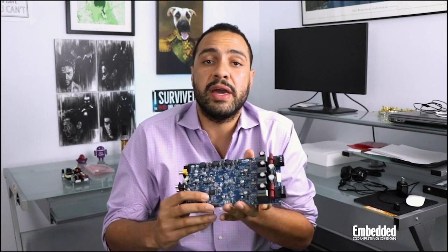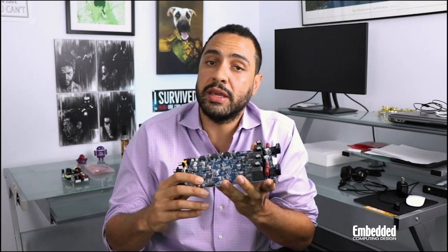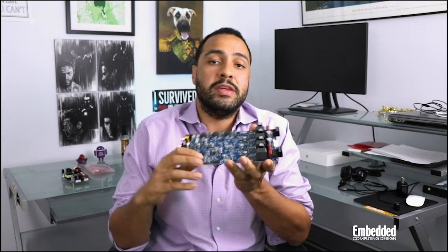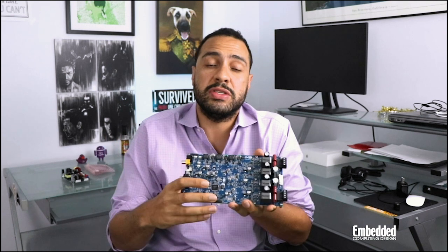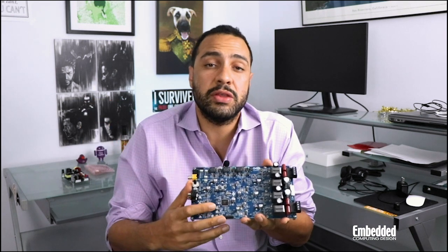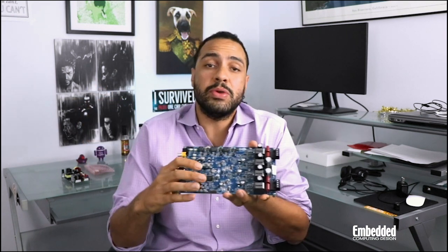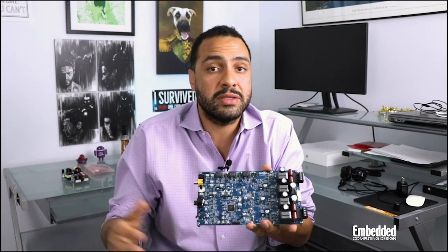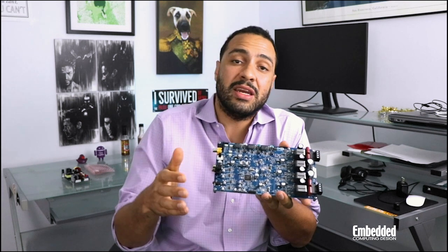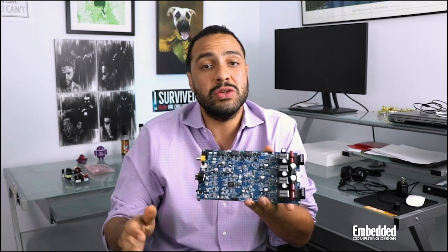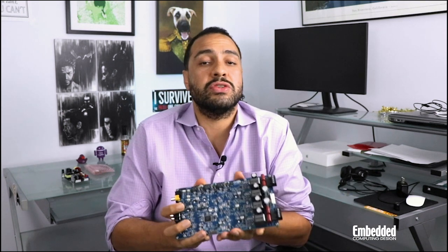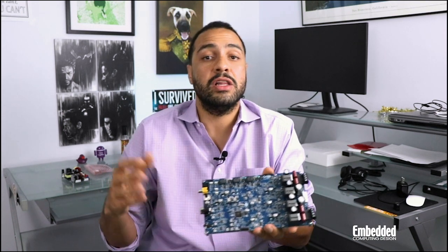Elsewhere on the board, you'll find a 24-bit Renesas D2 audio digital control processor that runs at 300 megahertz. The digital control processor also includes DSP features, integrated hardware accelerators, and a PWM modulation engine that can handle switching control and fault recovery tasks. Since these are conducted in dedicated hardware blocks, the MCU only uses 25% of its available MIPS, which frees up tons of other resources for tasks like UI functionality, low frequency control, and just general housekeeping.